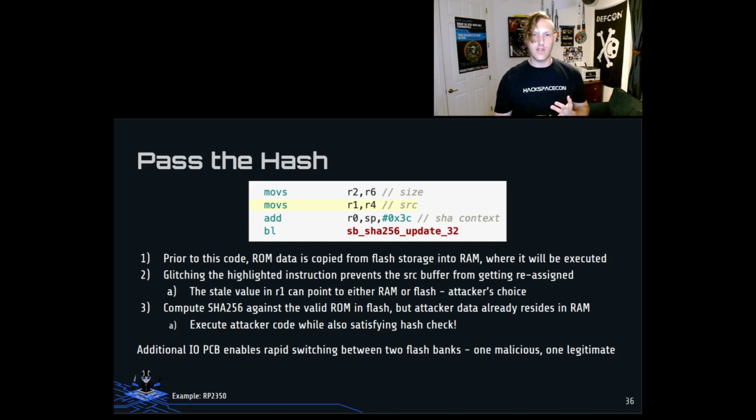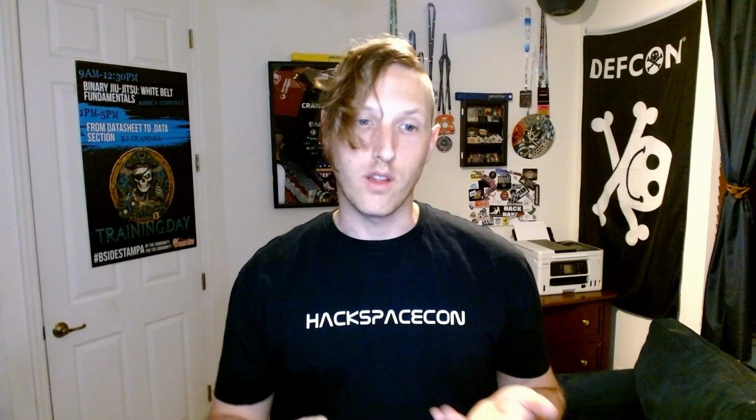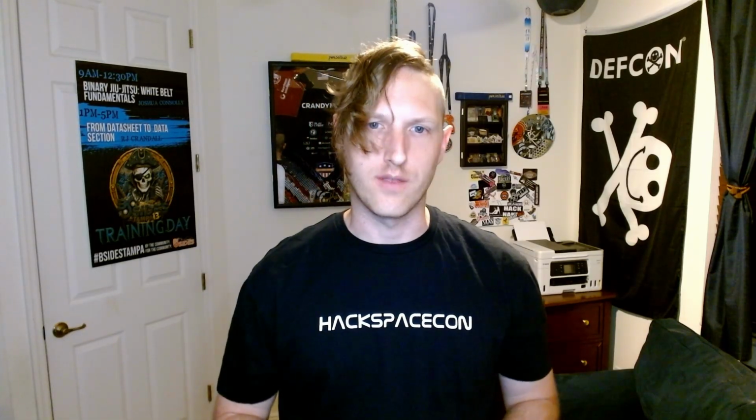It has two different flash banks, one of which contains malicious firmware, and the other one, the legitimate one, that will have a valid hash. Now, this is just one of the glitches that bypass the hash check. There were multiple other timings that glitched other instructions and caused similar issues, but they needed to be exploited differently.